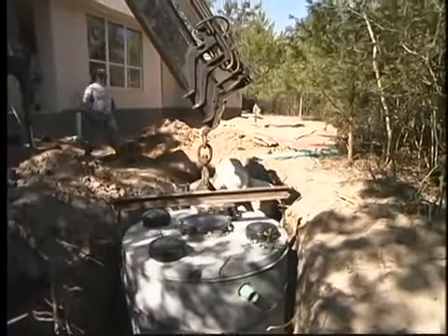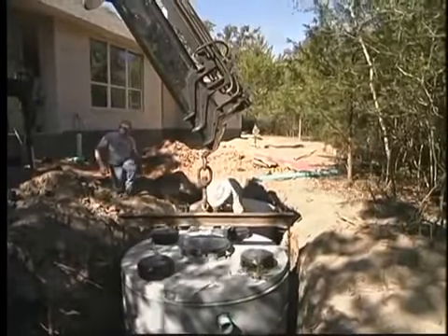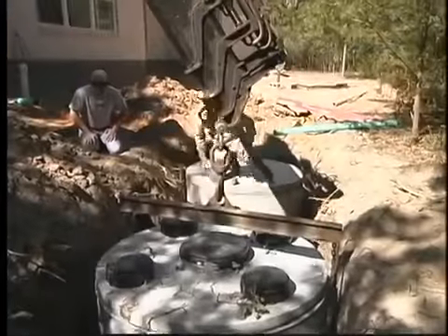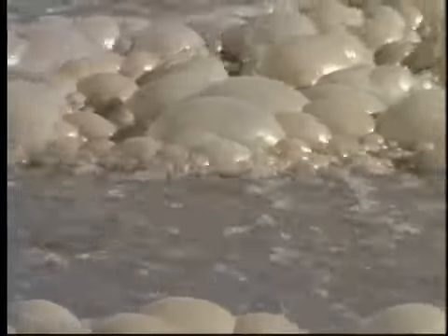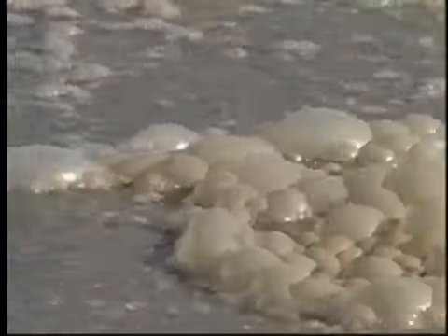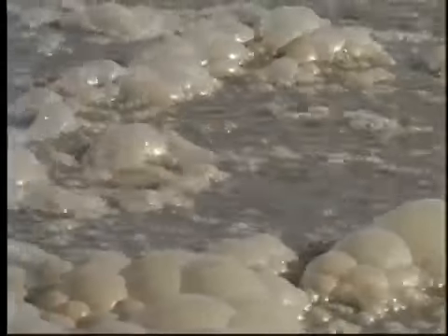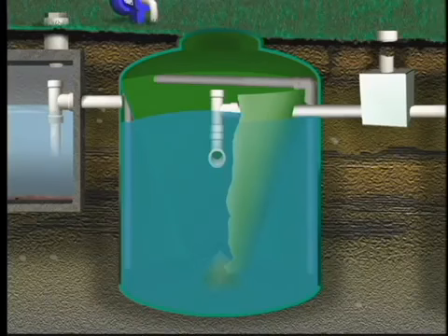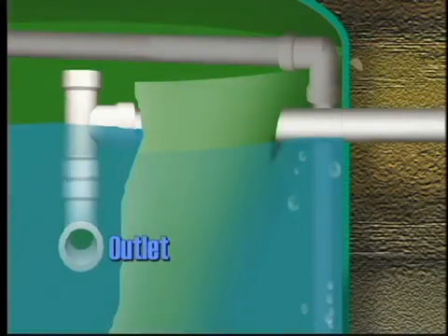Aerobic treatment units for homes and small businesses are similar to municipal wastewater treatment systems, just on a smaller scale. The effluent these systems produce is as clean as that from a municipal system, and cleaner than that from a conventional septic tank. These treatment systems remove a large percentage of the organic matter and suspended solids from the wastewater. However, water exiting the system can still contain organic matter, solids, nutrients, and pathogens.